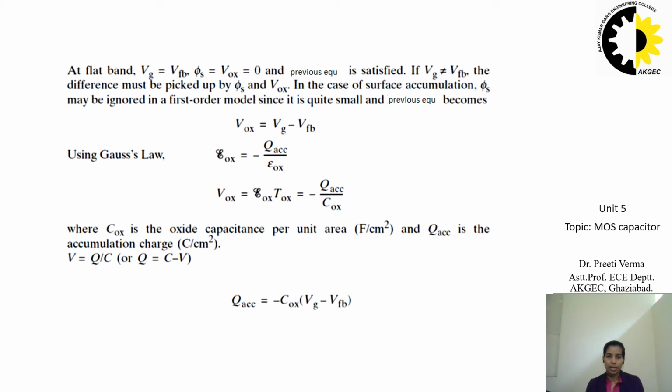In the MOS capacitor theory, the voltage is the gate voltage, but the charge is substrate charge, because interesting things happen in the substrate. This unusual choice leads to the negative sign in the above equation.